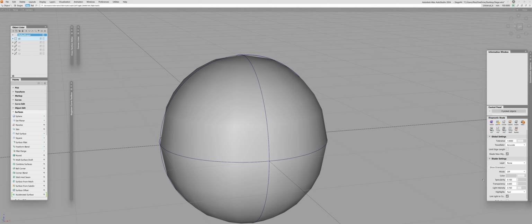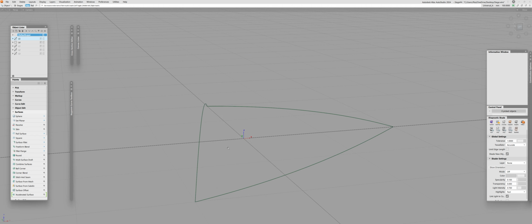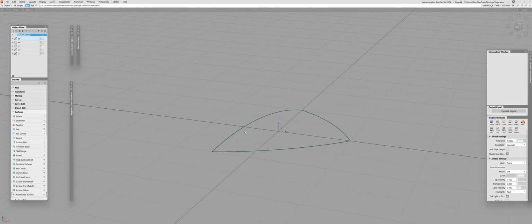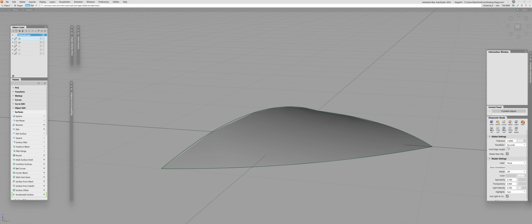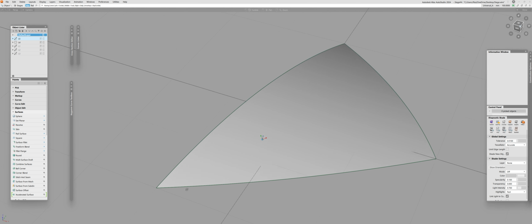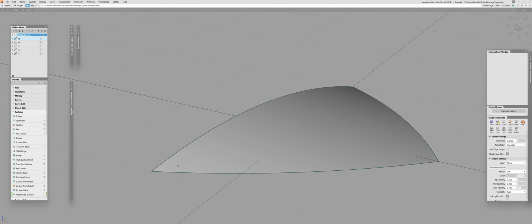And now we come to the practical question. What about it and why is it important? Let me show you. Let me actually hide this sphere now, and I will open up this example, this surface. Let me just turn that off, and let's increase the tolerance to something more manageable. Right. So if you watched my previous lesson about three-sided patches, you're familiar with the example. Now this is the flawed example. It has an issue because there is a degenerate point on the top, specifically here.